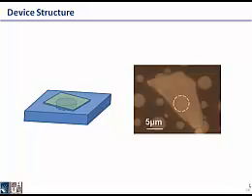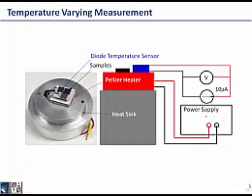So here, I briefly discuss how we explore our device operations and study these effects. When we started studying these, we wanted to quickly prototype a lot of devices, going through many of them to characterize them. So we chose a relatively easy structure, where we have a MoS2 crystal exfoliated over a micro trench to form a suspended structure. This way we can quickly produce a lot of devices and study their performance.